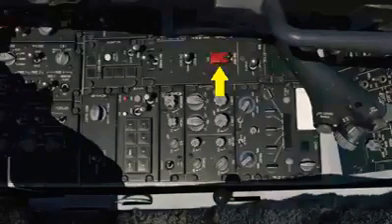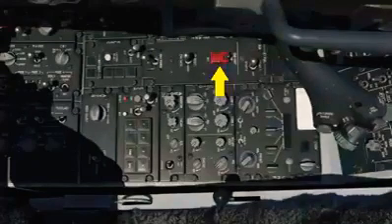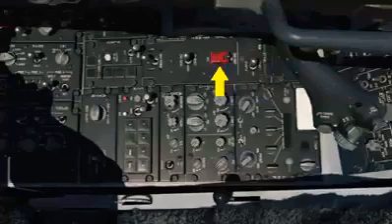Below is the guarded switch for the primary and secondary engine control modes. You normally have this in primary mode unless you run into a failure with the engine's digital electric control, in which case you can select secondary mode, or you'll have to cycle the engine to restart it after a flameout. Note that in secondary mode you have no afterburner.